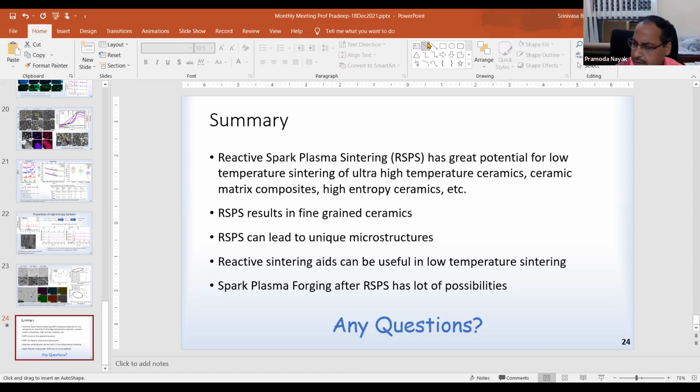Okay, and another thing: what types of material can you sinter with SPS? We are mostly talking about ceramic or ceramic nanocomposites, but can we do any metallic or some other system, or is any specific protocol needed for different materials? Yeah, we can even do magnesium, which is a reactive metal. We have done magnesium also because we operate at 40 Pascal pressure, and magnesium does not react under those conditions.